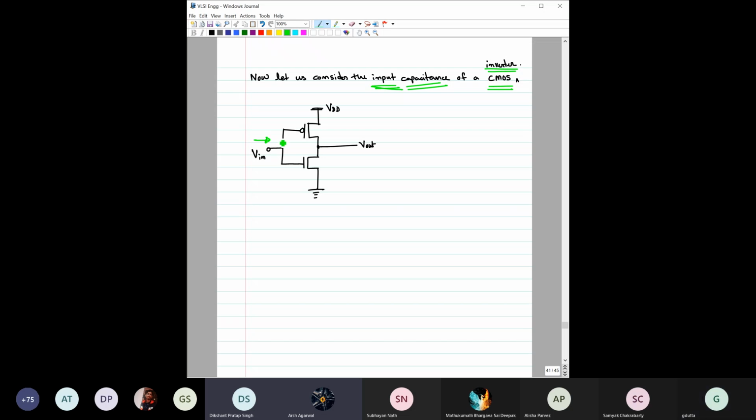For the cutoff transistor, there will be a major part from the gate body capacitance, and for the saturation transistor, we will have only the drain to body and source to body capacitances. So all of that would be added. What do you think the total capacitance would be?